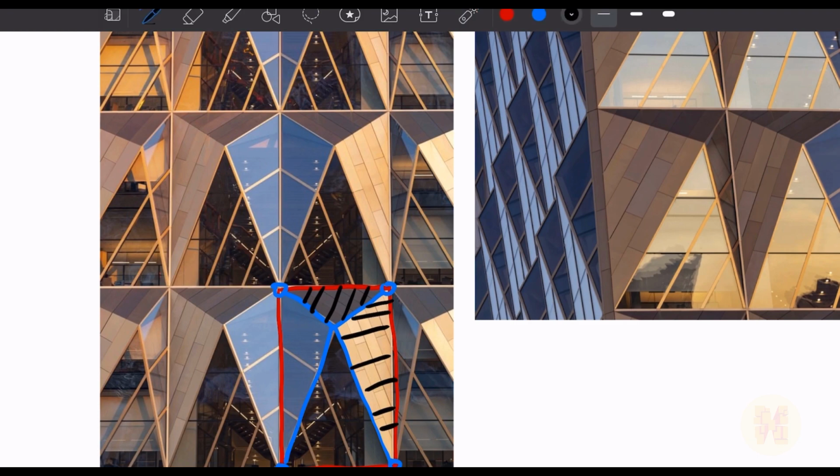So what I mean, let's say this is my secondary point, here, and to here. We can easily connect it by placing an adaptive family like a mullion. So we can create, for example, 2 more points here.